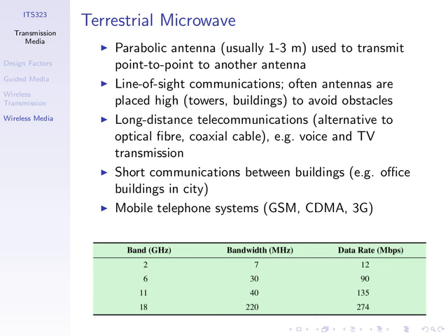The frequencies used, if we look at one of our previous slides, some of the higher frequencies used can be affected by the weather, the atmosphere and rain. Especially satellite, the next application, we'll see the frequencies are impacted by rain. That is, the signal hits the water and is attenuated. And therefore, the more rain, the more water, the weaker the signal will be at the receiver. And you may notice that in some cases if you've got satellite TV, the reception can be poorer if there's a large storm.